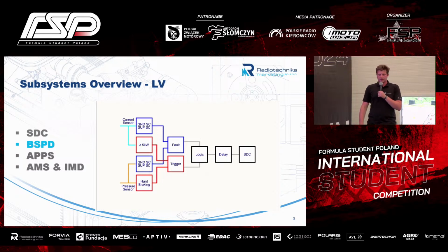It's really important to have pull-downs of signals on dedicated modules, so when you have an open wire problem, you don't have a floating input, because it's really problematic, especially with an electric car, when you can have some EMI issues and stuff like this.